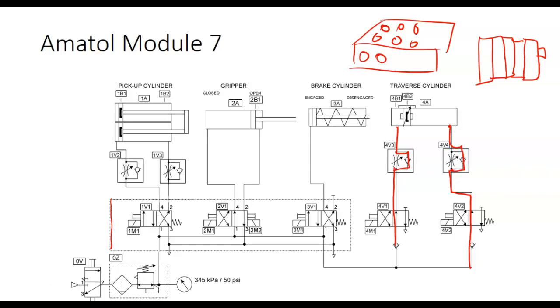Now, it's pneumatics, which means we can move it a little bit. If it's hydraulics, you couldn't do anything with it. Then what we do is we leave one of them alone and we shift the other one, and it'll cause it to move one direction. We leave one alone and energize the other one, and it'll move the other. Why they didn't do that, I don't know. It's acting like a three position valve, like the one we drew a while ago.